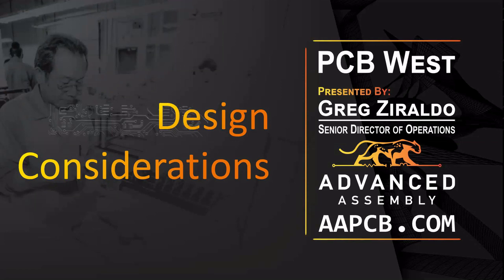To conduct more heat and electricity with your PCB while keeping the temperature down, you must increase the cross-sectional area of your PCB trace. There's two ways to increase the cross-sectional area of the trace, and that's to increase the width or the thickness, or both.